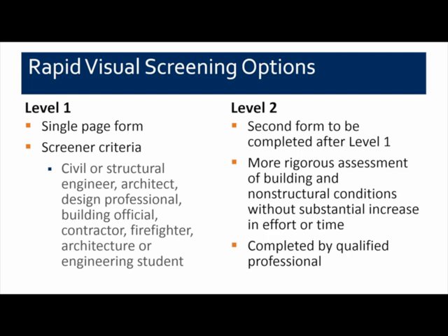There is an option for this level 2, which is another level or another page of form that can be completed. This requires a little bit more rigorous assessment of the building structure and the non-structural components with very little additional effort that might be required on the part of the screener. But this needs to be completed by a qualified design professional, an engineer preferably, that has experience in seismic design to make sure that this part of the evaluation is completed properly.